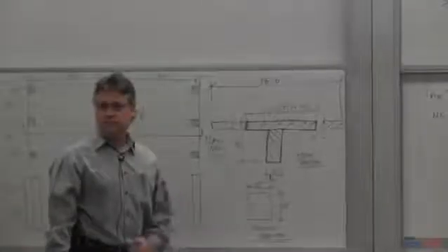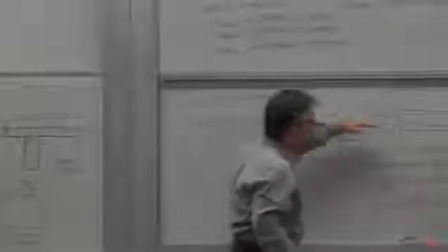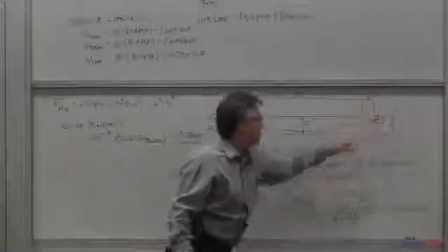Okay, I'm going to start with a good guess of 10 tendons. I already know the drape in the first bay, right? It's maximized. It's 4 inches from the bottom here. It starts at the CGC. 4 inches from the bottom here, 4 inches from the top there. So I've got a full drape in the long controlling span. That's what I want you to do. That's what we will do. And I'm going to start with